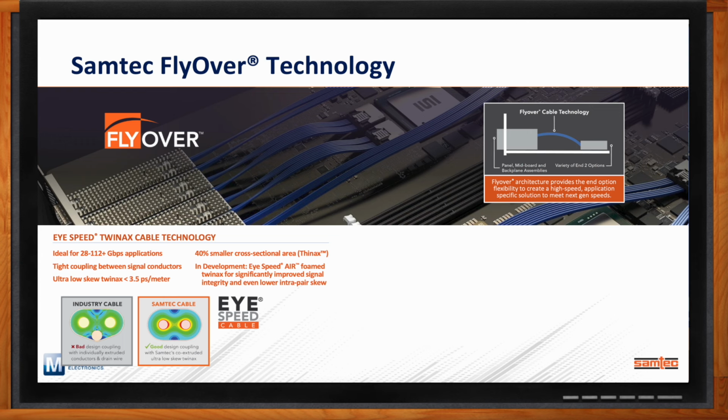But because we co-extrude ours, it provides signal integrity enhancements over everything else in the industry. It gives us tight skew, tight coupling between the signal conductors. It's also smaller. We have what we call our Twinax. It's 40% smaller, moved from one generation to the next. And we're also working on a third generation of our cabling technology that we call high-speed air.